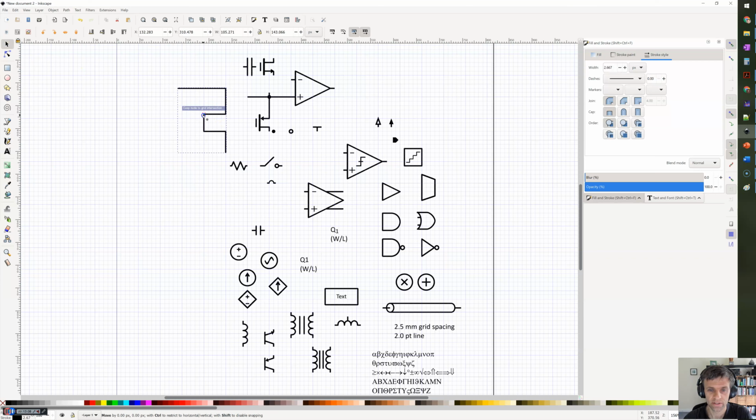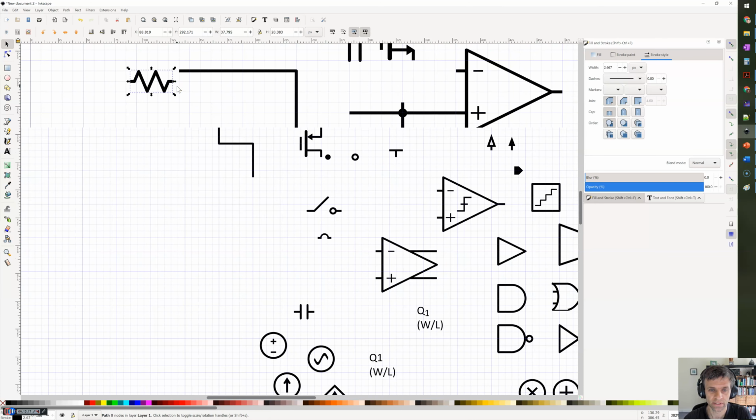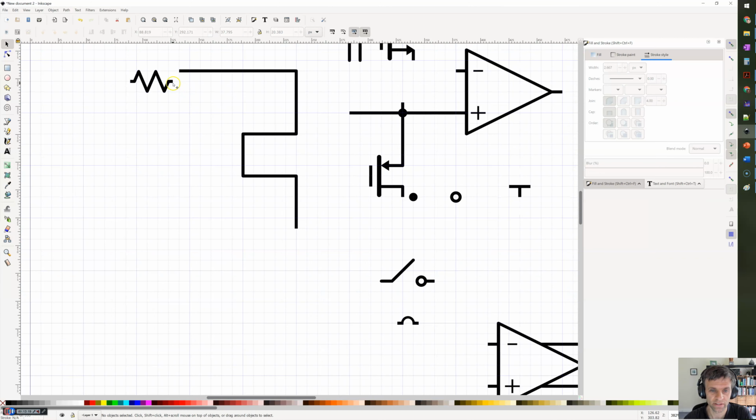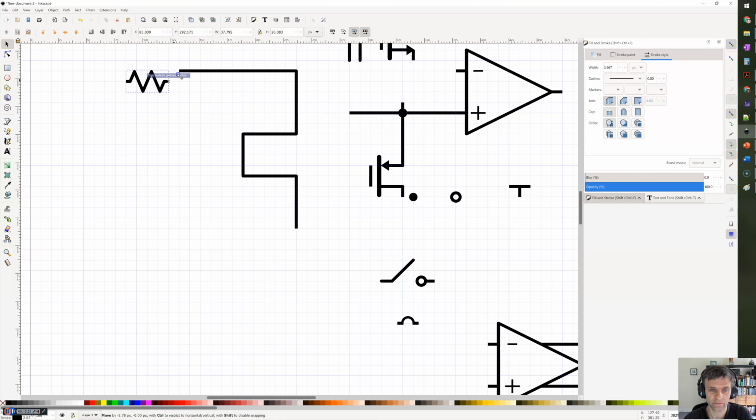Okay. So that's generally my desired behavior for most of the items here. Resistor, right? You want to zoom in and make sure you're grabbing the right snap point. If I grab the end of the resistor, right, that's a vertex in this path. I want to snap it to the grid. So I usually keep these points as being the selection points for my snapping.